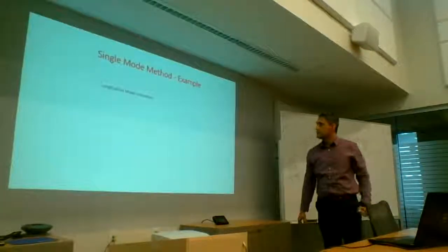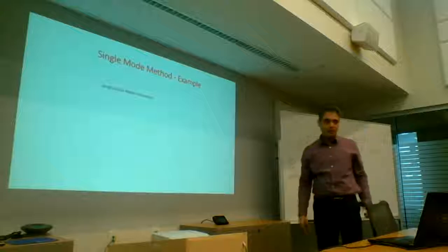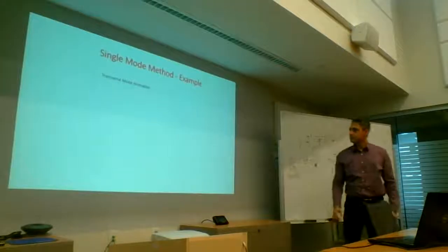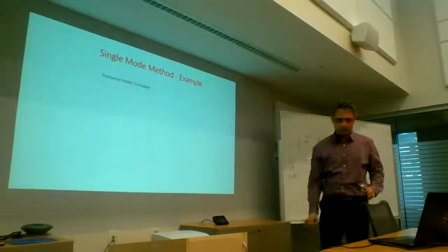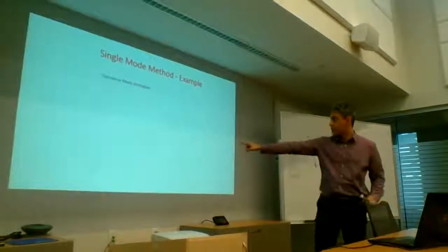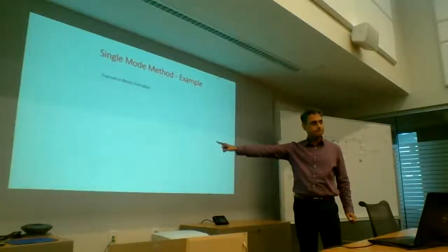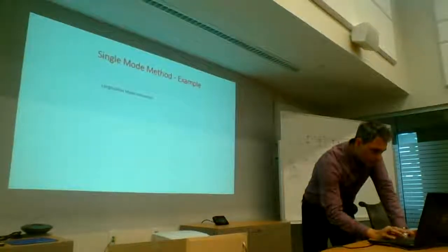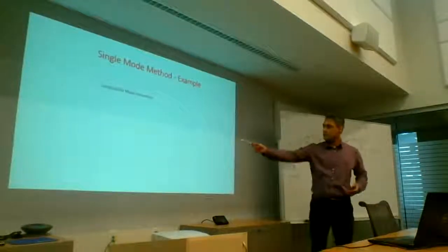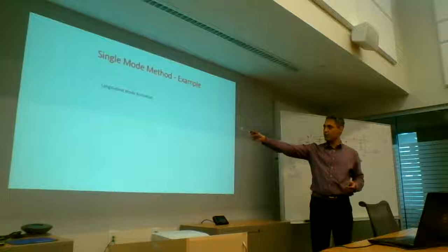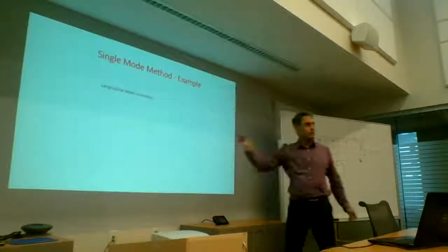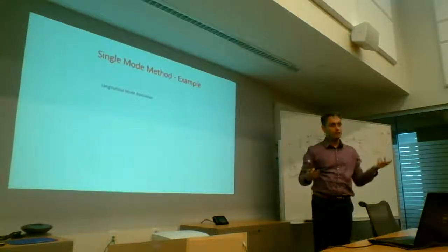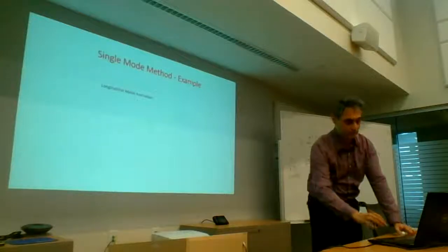Yeah. So this is just showing you the longitudinal mode. It's amazing that this is still working. And you can see here, your columns are going into double curvature, right? You can see the double curvature on the columns. In this case, you see they're fixed at the bottom, but there is nothing to force that. Because these two points are free to go, they're working as a cantilever. So they're going in single curvature, and hence the 3EI over L cubed stiffness versus the 12EI over L cubed stiffness.